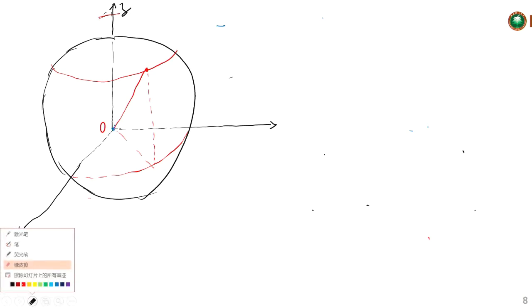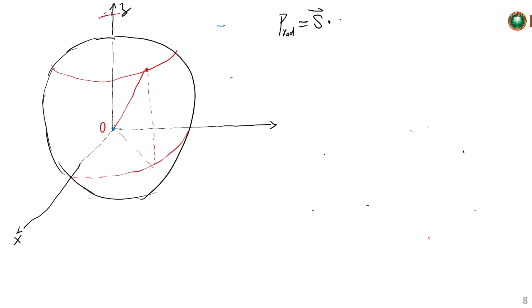For the power density S, if we want to convert it to power, the radiated power, it should be multiplied by area. So if our source is at the origin, we take integration all over this sphere, and we can get the total radiated power by this antenna.